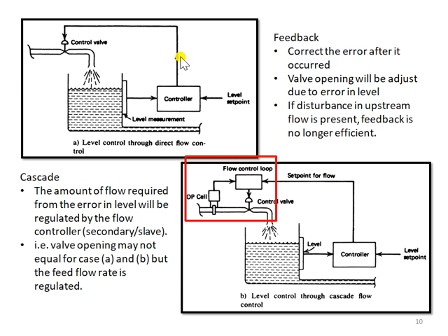the valve opening. So all the problems due to the unregulated flow rate are now handled by the secondary control loop. So the performance of the controller, which is the water level, will be much better as compared to the controller without cascade.